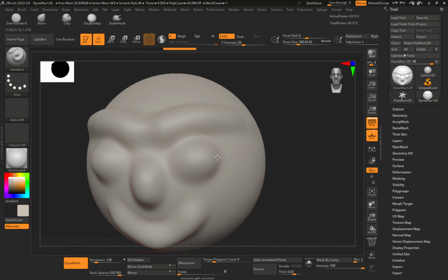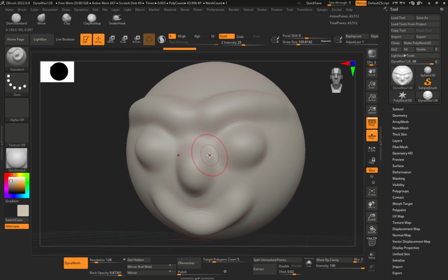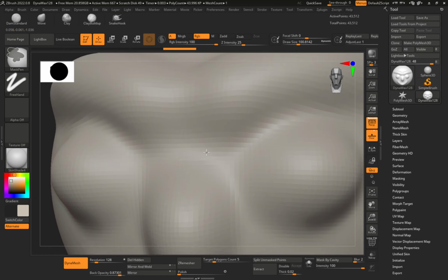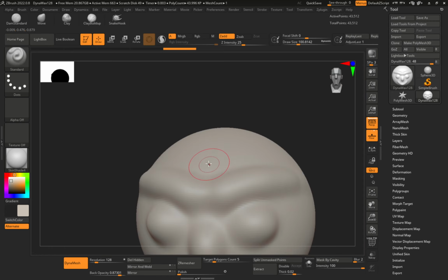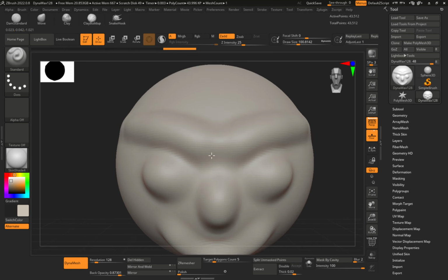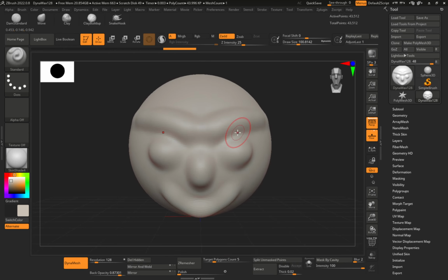Okay, you can move your camera around. All right. Last but not least is the zoom. Hold down Control, then right mouse button down and hold. You can zoom in and out of your object. Cool? Cool. And then if you hit F, that just reframes your object right there. So I'm going to right click and hold and press down Shift again to snap it back to the front view. Okay, so those are the basic commands for your ZBrush.